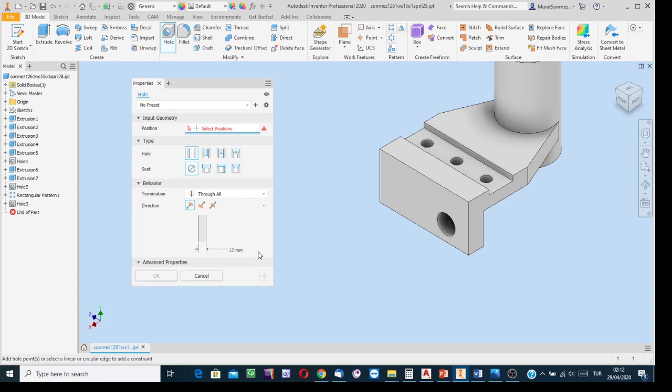Okay, diameter is 12, starting surface is this one. And then the location dimension from this edge is 10. From that, I don't want to indicate the edge of the circle, so say other hole, indicate this reference feature, and then make this calculation. 15 plus 30 makes 45.